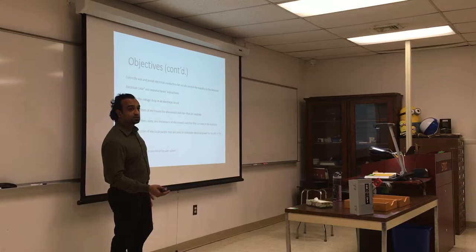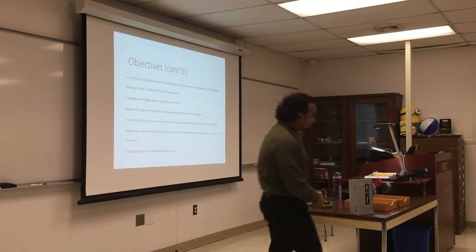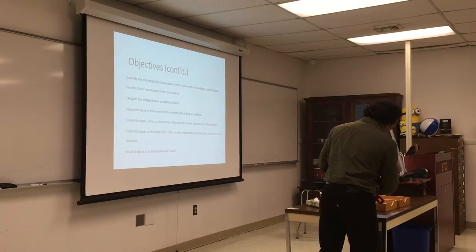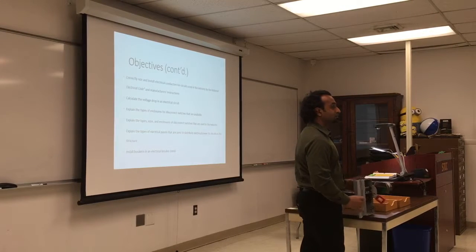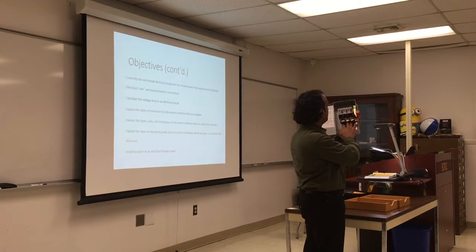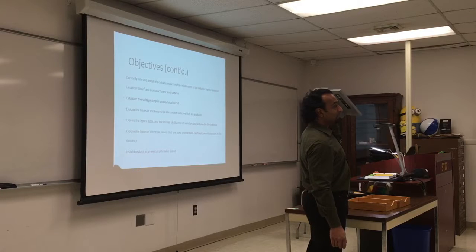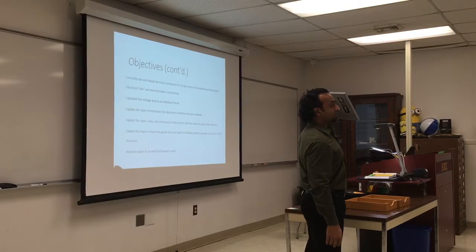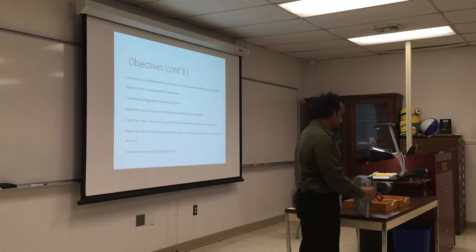Some of them are fusible, some of them are not fusible. If you can remember fusible and non-fusible, let's look at this one. Is this fusible or non-fusible? Fusible. This is fusible. It has a fuse in each line. And if you notice, it's also three-phase. The fuse only is placed on the hot line, so we have 3 hot lines. So this is probably 3-phase. Actually, it is 3-phase with fuse on them.